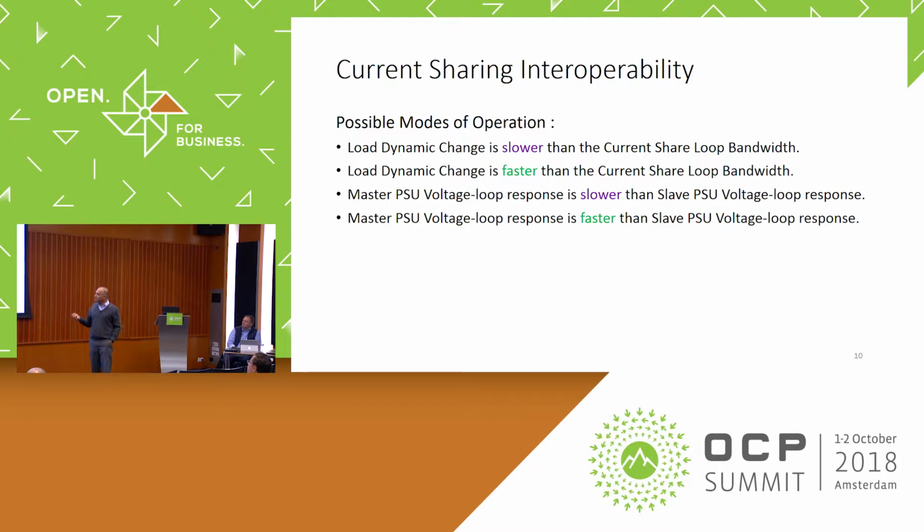Without getting into detail, when we talk about master and slave, that's a terminology commonly used in the power supply world. The power supply that has the higher voltage has the maximum current. So that's called the master. And there is a certain level we maintain. The other one is called the slave, which has slightly lower voltage. So obviously that will carry slightly less current. So ideally, if you take the whole operation, you can divide that into 4 possible combinations of operation.